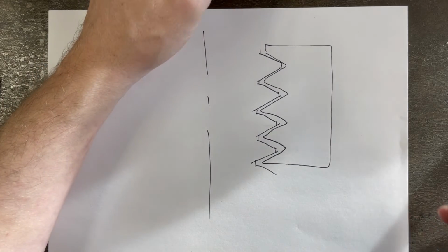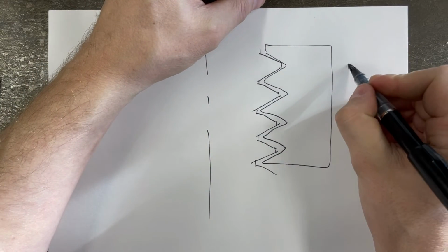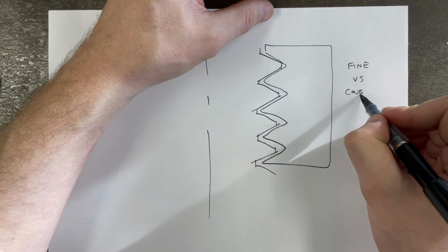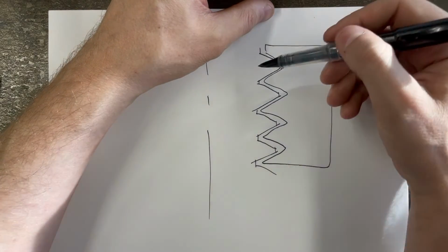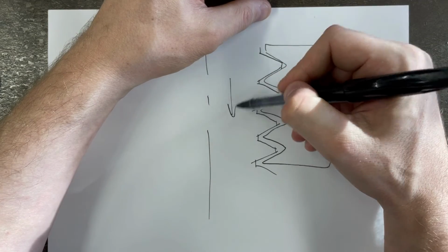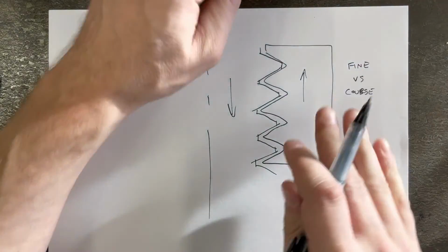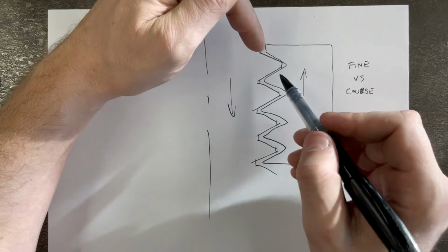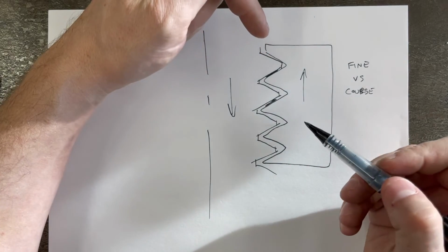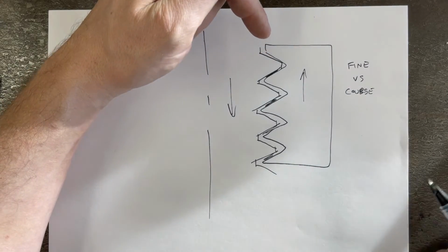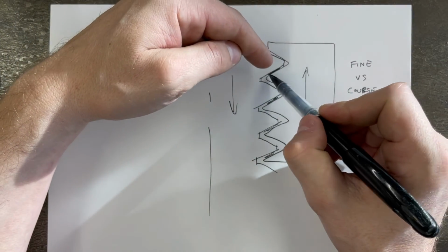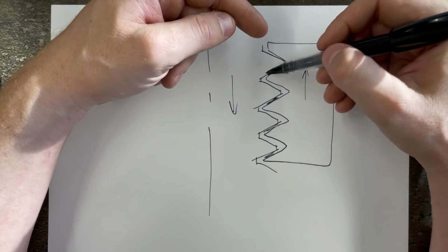Okay, so I'm drawing here. I want to talk about fine thread versus coarse thread, to kind of just touch on some of these ideas and principles. If we're tightening up a nut on a cap screw, these two are going to be put in opposing forces. So the point that's going to take those loads or those forces are going to be the flanks of the bolts. Now, it's important to understand that the flanks and these threads are going to be put in shear.